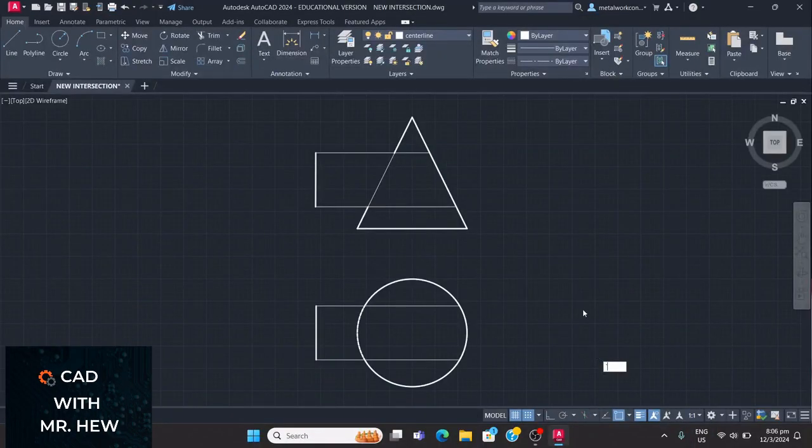All right. Now, in today's lesson, we'll be drawing the intersection of a horizontal cylinder that's horizontal to the base of the cone, and we have a cone represented by a triangle in the front elevation, and in the plan the cone is represented by a circle. So what we have is a cylinder intersecting the right cone, and we want to know what is the line of intersection that is formed when these two geometrical shapes meet or intersect, right? Hence the name, the topic, intersection, and some books call it intersection of solids.